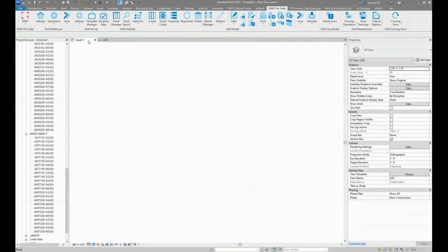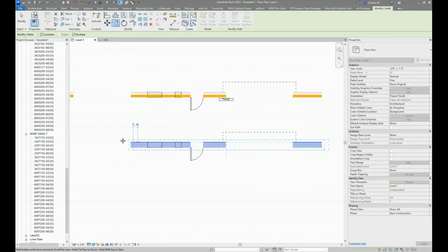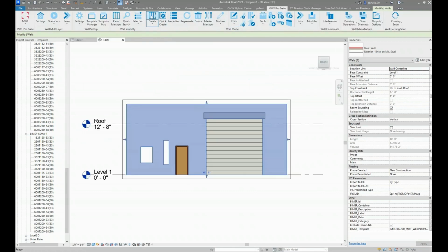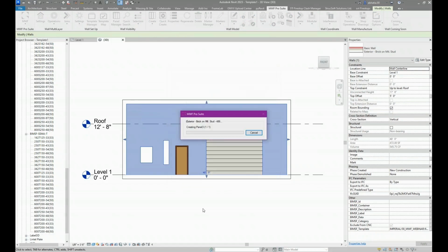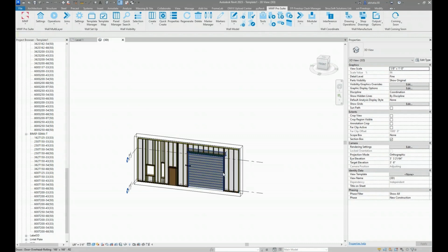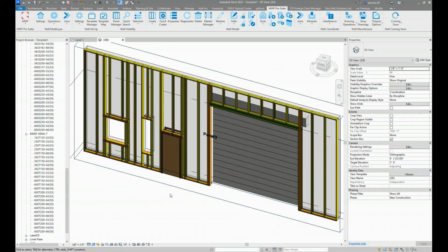There you go. And again, my last test is to test the test wall. So I'll bring that over here, go into a 3D view, and just double check if everything that I've done and said has been saved to the template. Set as active, close, create. And I do this with almost every template whenever I do implementation for clients. I make sure that everything is done correctly, because if you don't test it, you won't know what went wrong. So I do this for every different type of wall and fun things like that.